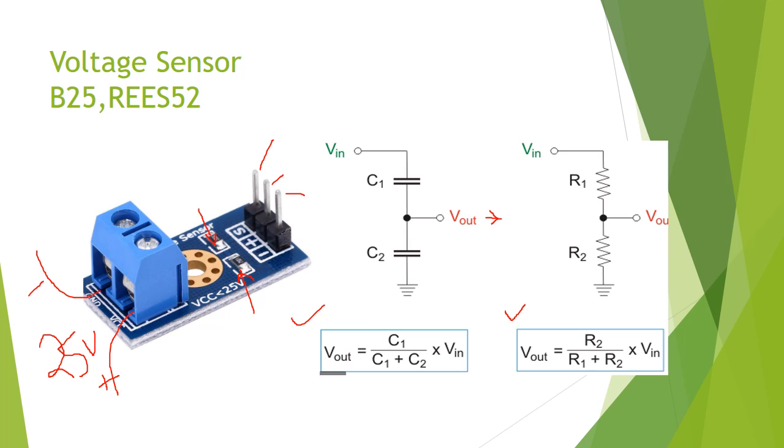That's why, if you have seen the CRO and a CRO probe, and the measurement there, almost 90% of signals are in voltage. You have seen a voltage signal in the CRO, you have not seen a current signal, because a voltage signal is quite easy to measure. You just need to step down the voltage to the electronics level on the CRO.